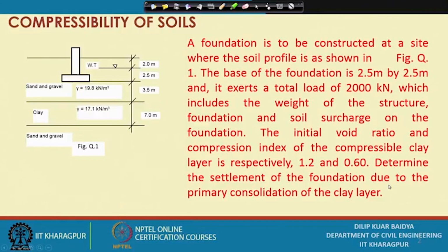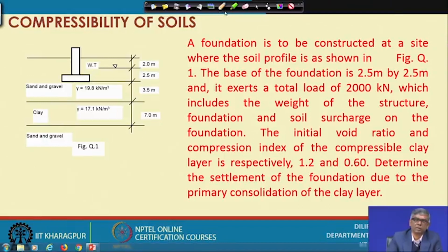You can see, though we have not learned geotechnical engineering, foundation engineering, this is the thing one has to understand: at the end of every column there will be an enlarged base, which is nothing but footing. Why do we enlarge this? To reduce the pressure. This column is carrying some load, and if I directly put it here, the soil will not be able to bear that much pressure. To reduce the pressure, we enlarge this one, this is the footing size. So, footing will be much bigger than the column size.